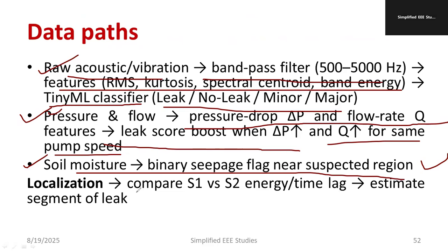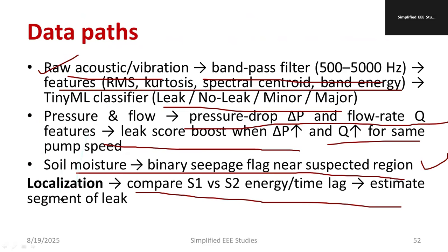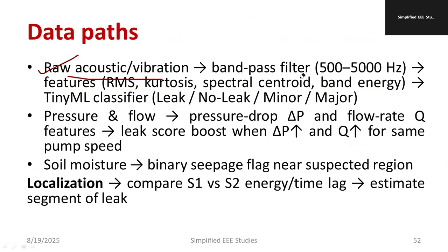With respect to localization, compare S1 and S2 energy time lag, and estimate the segment of the leak. Based on the position of the sensors, we can identify the difference. If you compute it, you can identify where exactly the fault has happened. These are the basic strategies you have to apply.